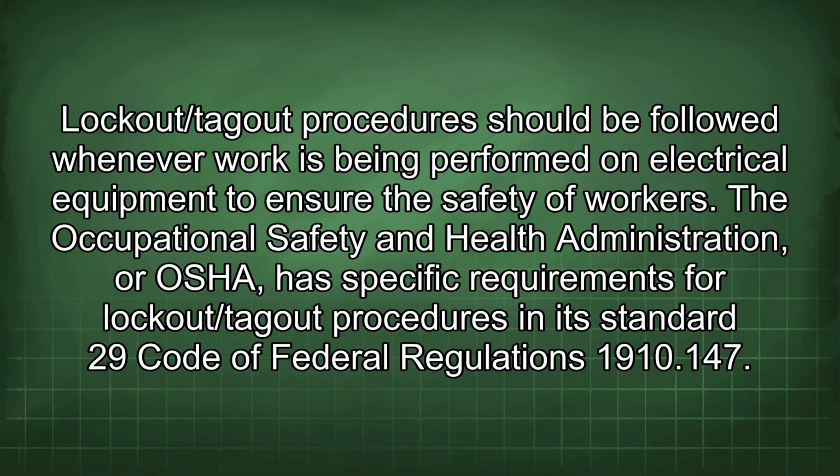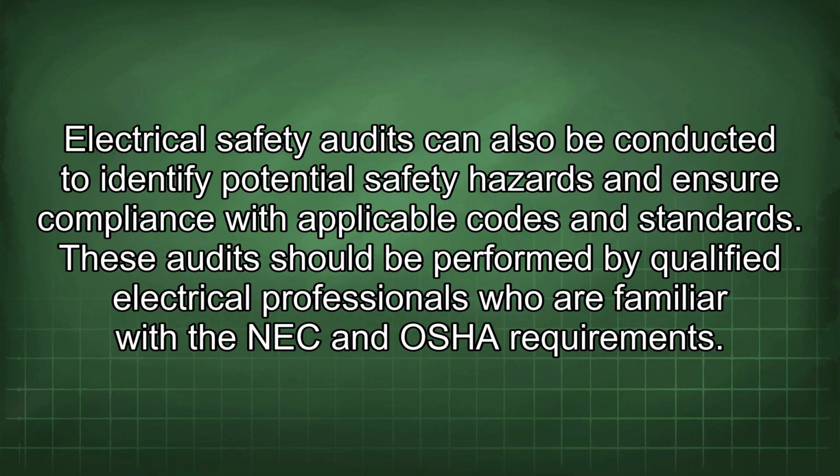The Occupational Safety and Health Administration, or OSHA, has specific requirements for lockout/tagout procedures in its Standard 29 Code of Federal Regulations 1910.147. Electrical safety audits can also be conducted to identify potential safety hazards and ensure compliance with applicable codes and standards. These audits should be performed by qualified electrical professionals who are familiar with the NEC and OSHA requirements.